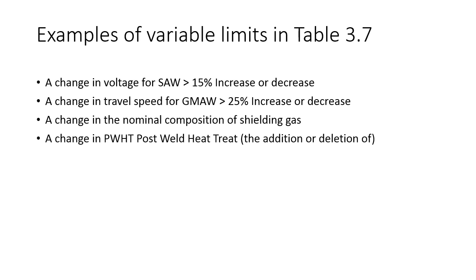Change in the post-weld heat treat. A lot of times you don't use that in structural, but if you add post-weld heat treat to a weld, or you remove post-weld heat treatment from the weld, then you need to address it and rewrite your procedure.